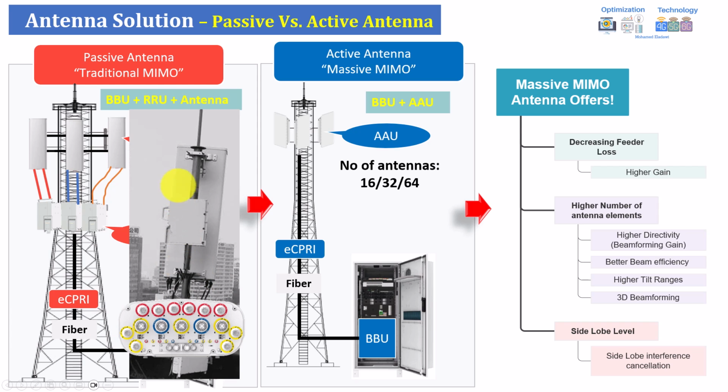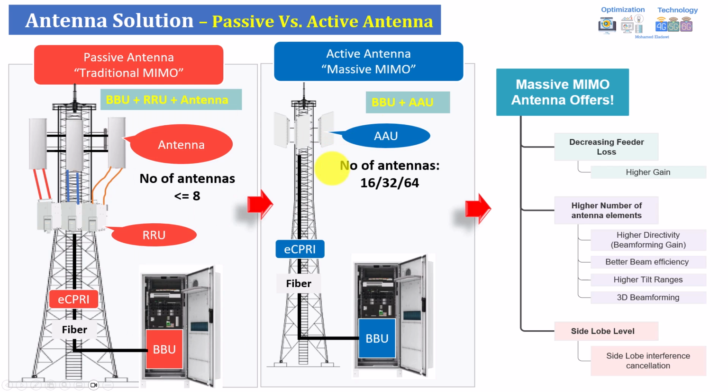Usually the traditional MIMO, the passive antenna in general, is used for different technologies. It can connect 3G, 2G, and 4G, and I think in the future some of it can even support FDD-NR. For example, here there can be ports used for 1800, 2100, 800, 700, 900, and so on. You would call it, for example, GUL, which stands for GSM, UMTS and 4G. For the active antenna, the main difference is again where we highlighted.